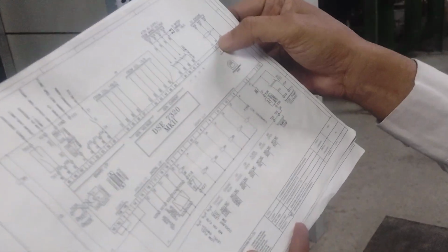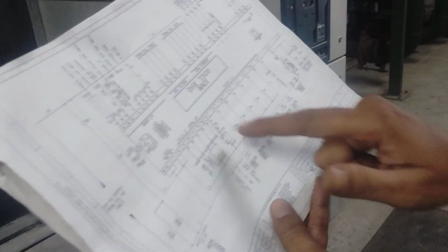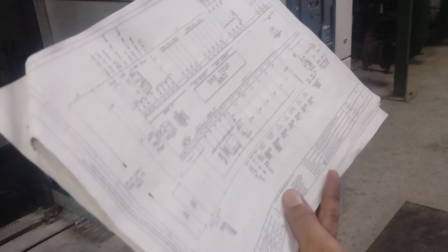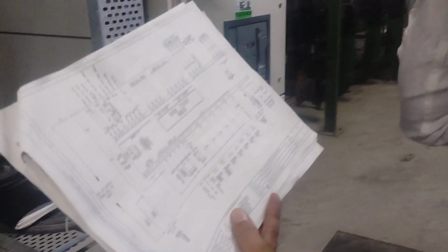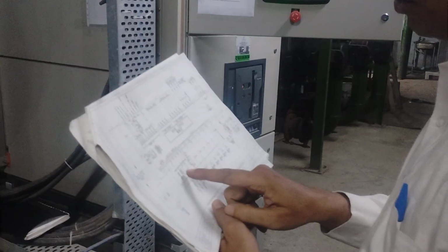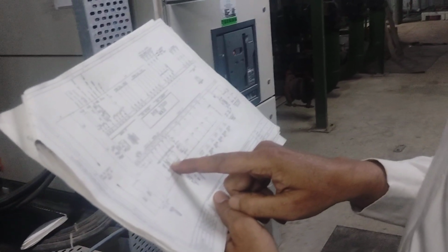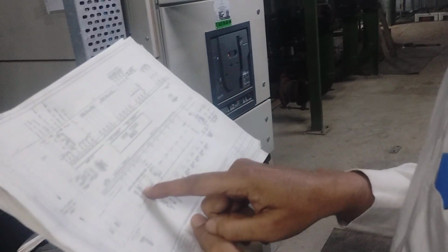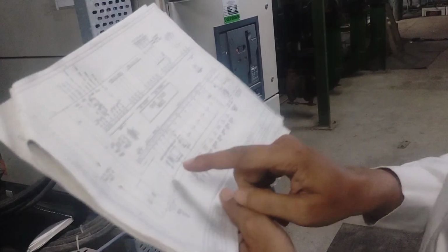And these are the various inputs which are connected and configured to the DSE electronics. This is the MPU sensor for the speed controller. These are the remote start, stop, breaker control, breaker on, off, and engine crank, engine run. These are the analog inputs for the oil pressure sensors and coolant temperature sensor. The oil pressure sensor is a VDO 10 bar, a diaphragm based transducer and sensor, and this is the coolant temperature sensor PT100. This is also a resistance based analog input for the temperature controller, and for the VDO 10 bar it is the oil pressure sensor.